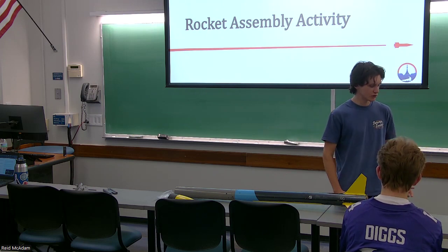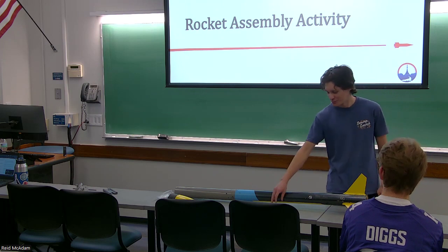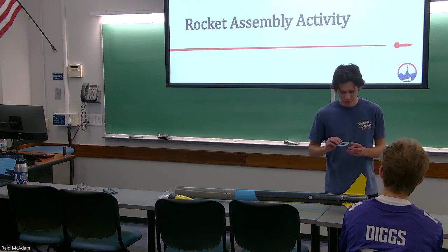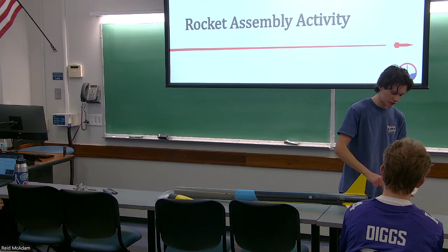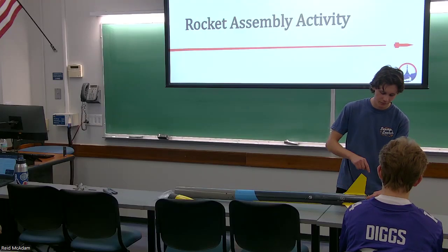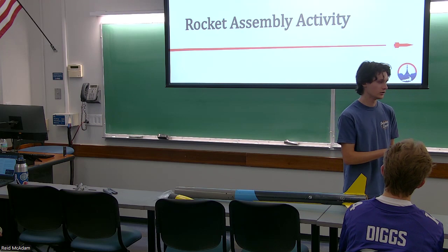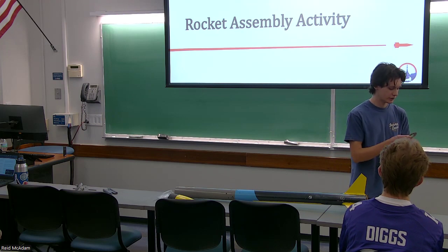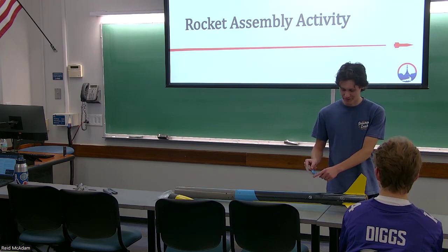The issue with that is if we're just sliding the motor in the bottom, then when it's on the launch pad, it's just going to fall out. That's what this little motor retainer is for. So basically the motor goes in, and then we put this little motor retainer just on top of it, and then screw it into the centering ring. And it's got a hole in the middle for the flames to come out. Mostly at least, you can see it burn on, even more there.